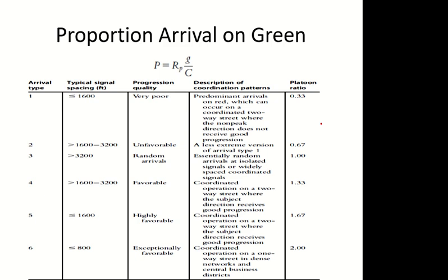And the cycle time is the total time of the signal, when all movements are completed, when all phases complete. So effective green upon the total time of the signal gives the G by C ratio.